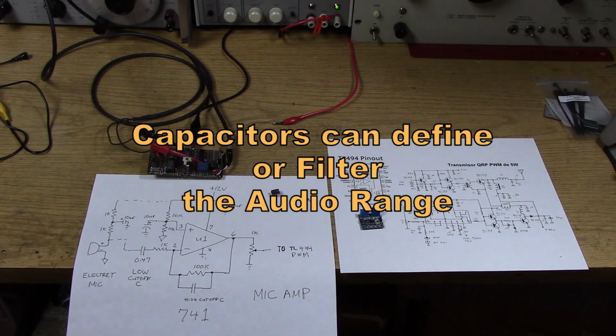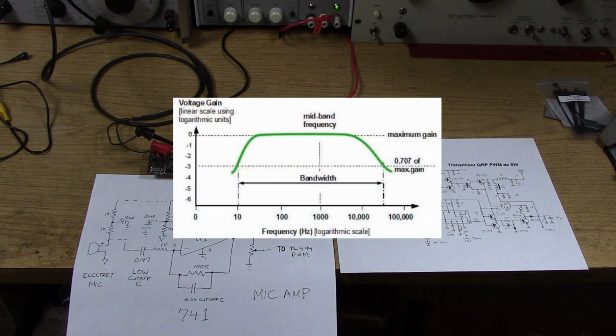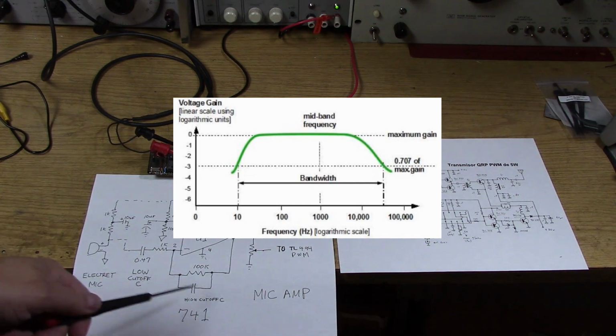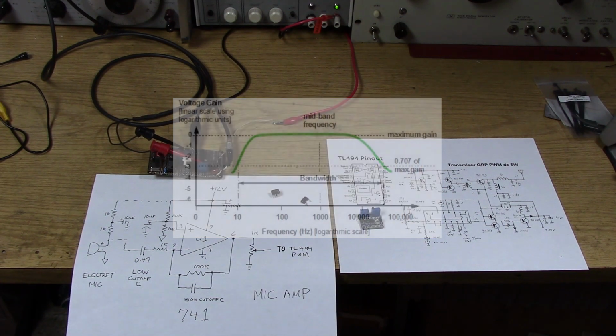Also, putting a capacitor in the feedback allows you to shape the high side, and we can get our 3 dB point or 6 dB point if you want situated. I don't want to have a really wide transmitter, so I'm going to try to have my 3 dB point around 5 kilohertz. I think that's reasonable.